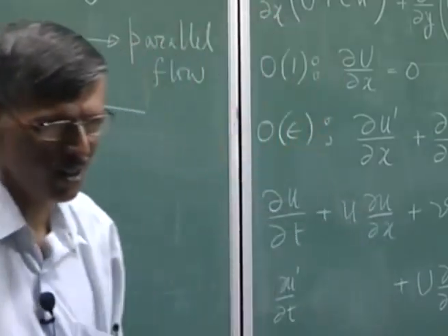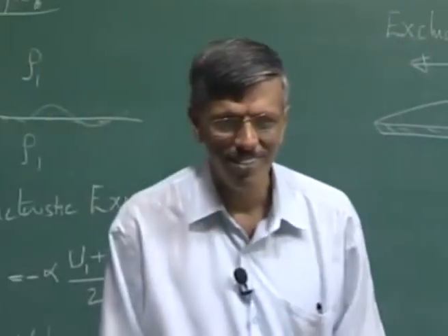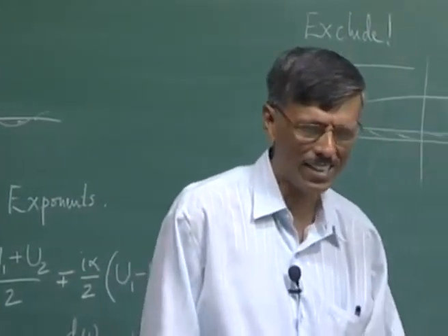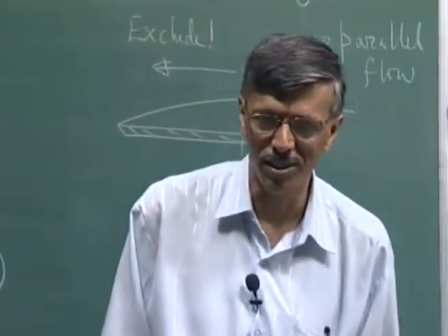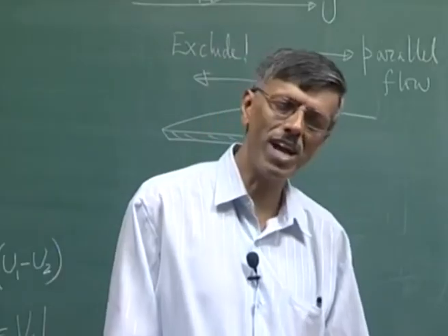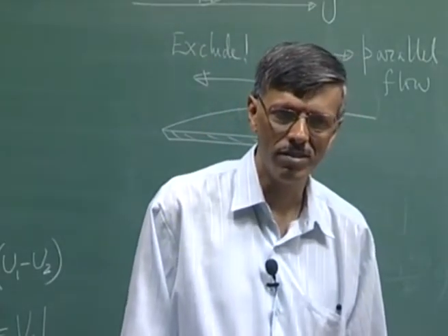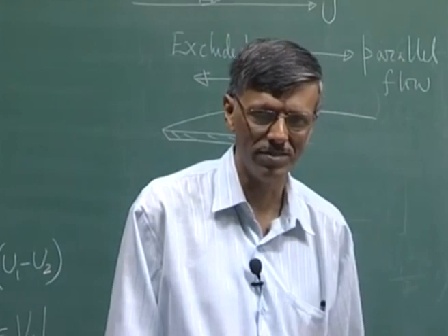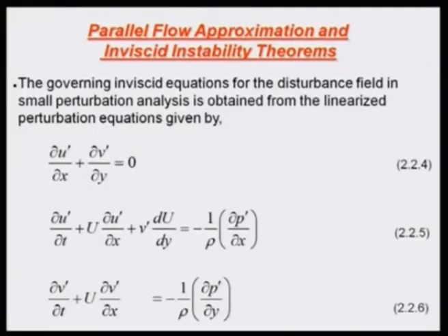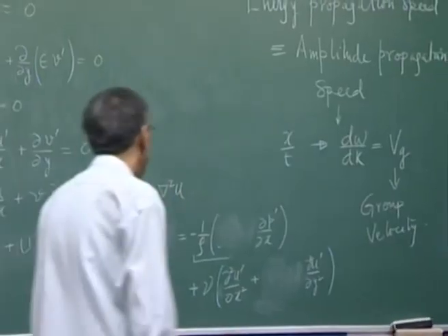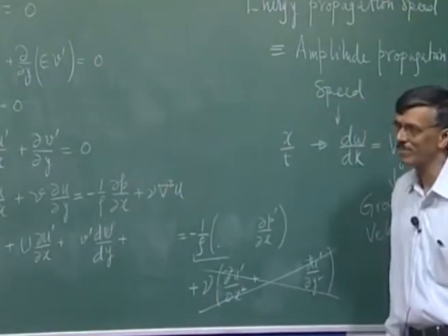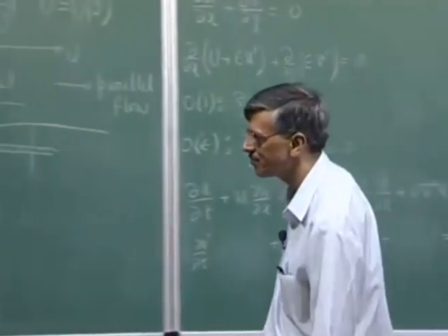Of course, this is a similar approach here, because we cannot handle the full thing, and then as an afterthought we say viscous action is there, it has to attenuate. So, let us try to find out the more critical case by dropping the viscous term altogether. That is the essence of inviscid instability. Inviscid instability would mean that we do not need to look at this term, and that is what you are seeing here,